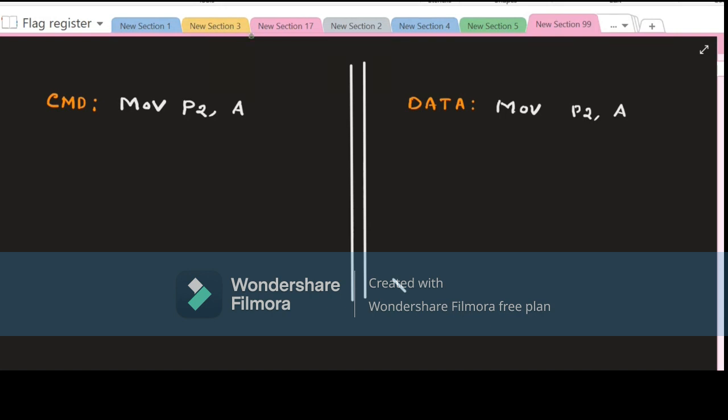Now just after that, we have to decide whether you are sending a command or sending data. This is the RS register. RS equal to 0 is a command, and RS equal to 1 is for data. And this RS pin is connected to port number 1, bit number 0. So we know this RS pin is connected with this pin number.